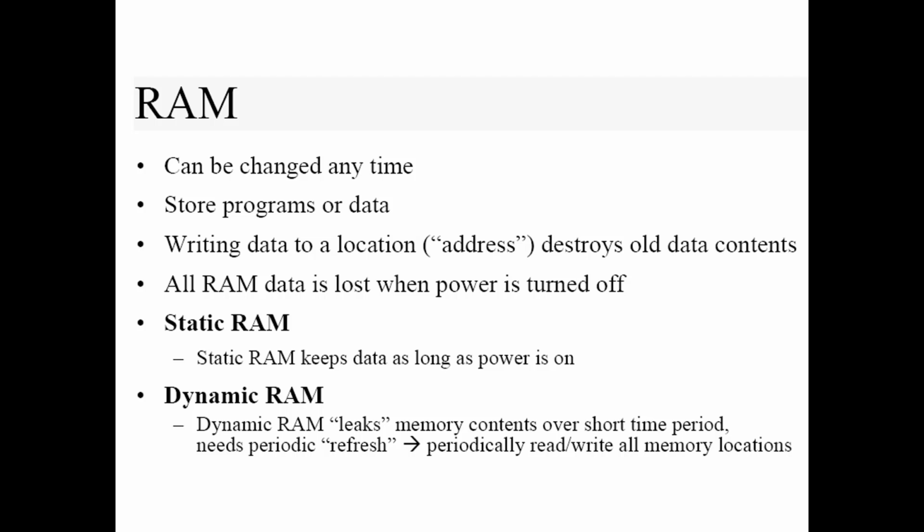Applications of RAM in embedded systems: we have data storage, that stores variables, buffers, and other data that the CPU needs to access quickly. Program execution, that holds instructions that the CPU is currently executing. Temporary data, that is used for temporary data storage during computations and processing tasks. An example of which is microcontroller RAM. In microcontrollers, RAM is used to store the stack, heap, and global variables. It provides a necessary workspace for the CPU to perform its tasks efficiently.